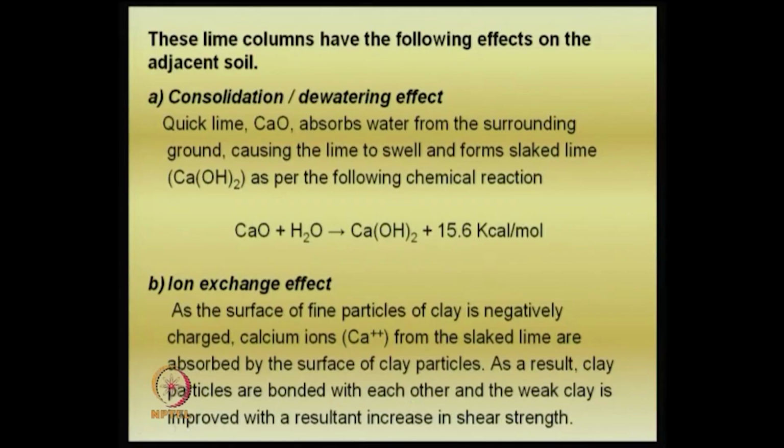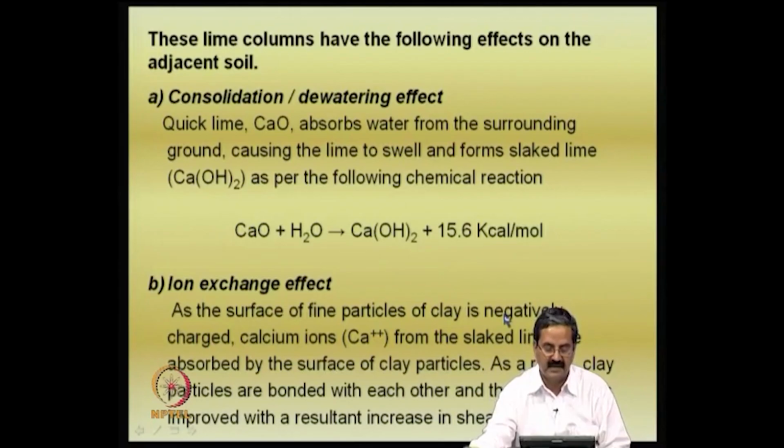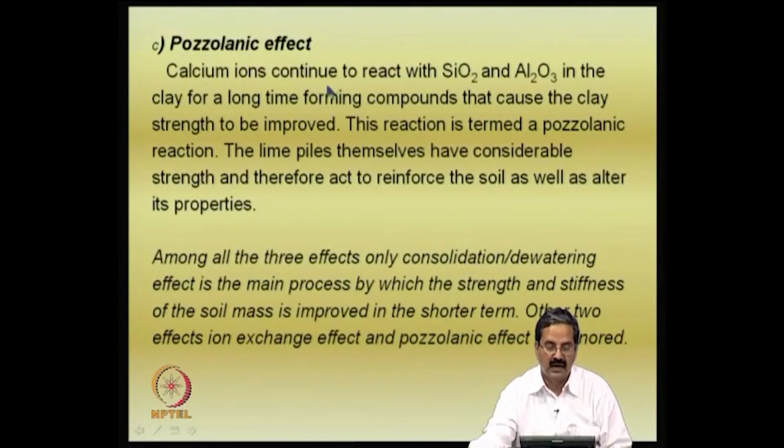Even the lime columns have the same thing, except that quick lime, as I just mentioned, forms slaked lime. This is quick lime and this is slaked lime, and then you have the heat of reaction, and ion exchange takes place. The same mechanisms also control the stone column or lime column behavior, and pozzolanic activity, the pozzolanic effect, is also there.